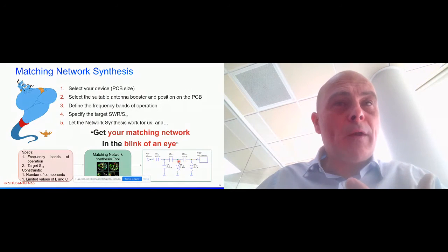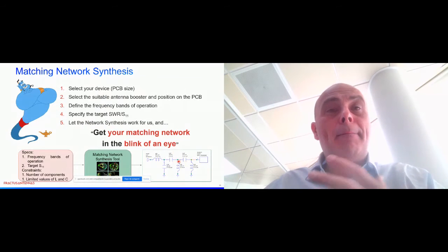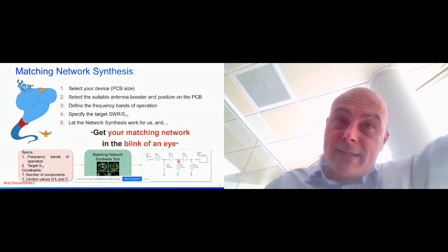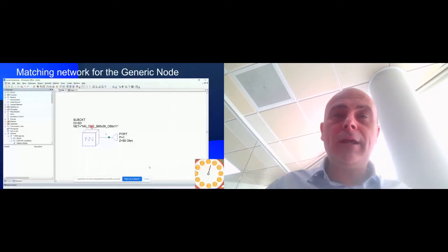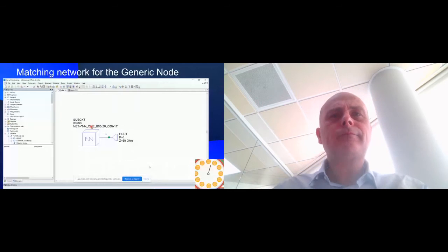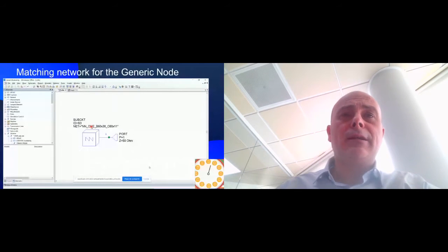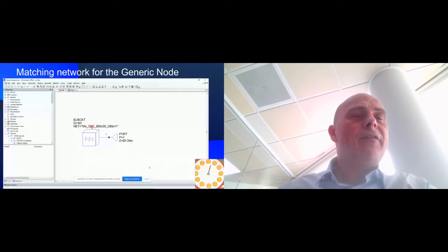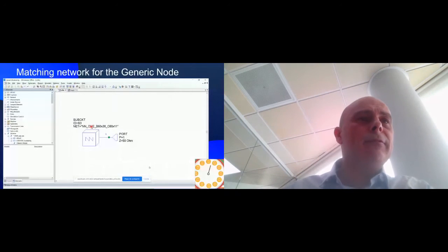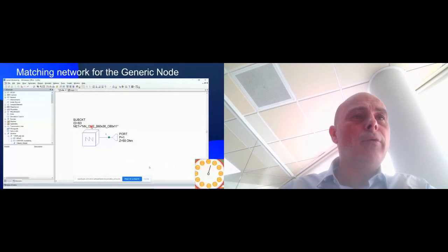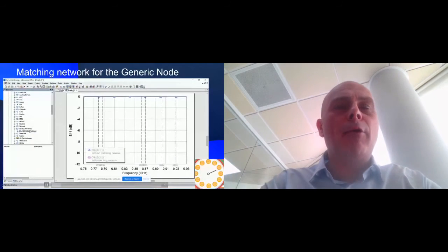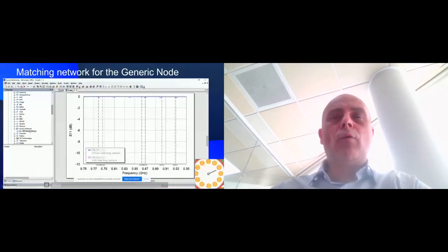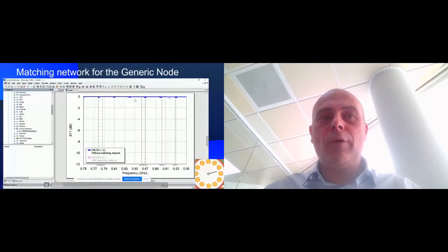This is how the S11 file looks like. It's a black box containing the S11, the impedance data for the one on the PCB 60 by 30. And let's run this video. Let's have a look. And this is the file without any matching network. This is the first time ever that you have antenna library, you can see here, embed in a circuit simulator. We have components. In this case, we have the Fractus Antennas virtual library embed in Cadence AWR. We see the S11 is very poor because we don't have any matching network.